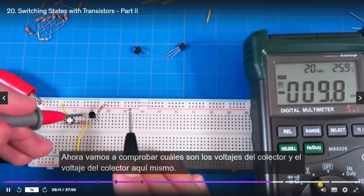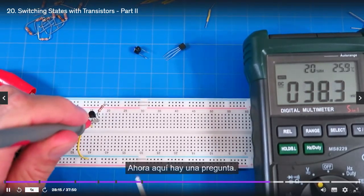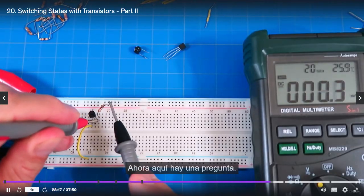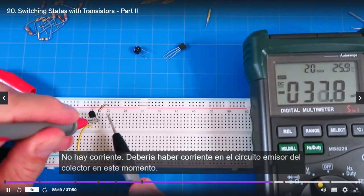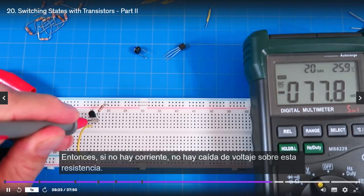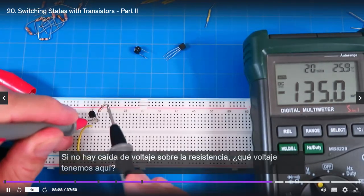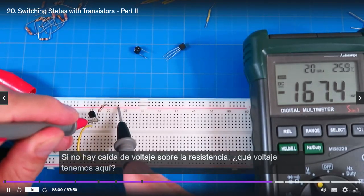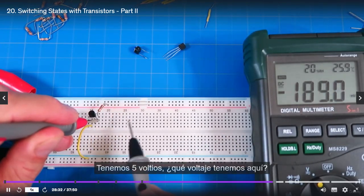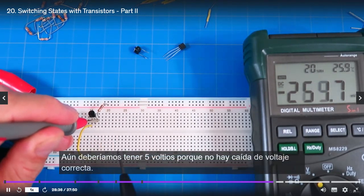Okay, now let's go check what the collector voltage is, and the collector voltage is right here. Now, here's a question. There's no current, there shouldn't be any current in the collector emitter circuit right now, because there's no base current. So if there's no current, there's no voltage drop over this resistor. If there's no voltage drop over the resistor, what voltage do we have up here? We have 5 volts. What voltage do we have right here? We should still have 5 volts because there's no voltage drop.